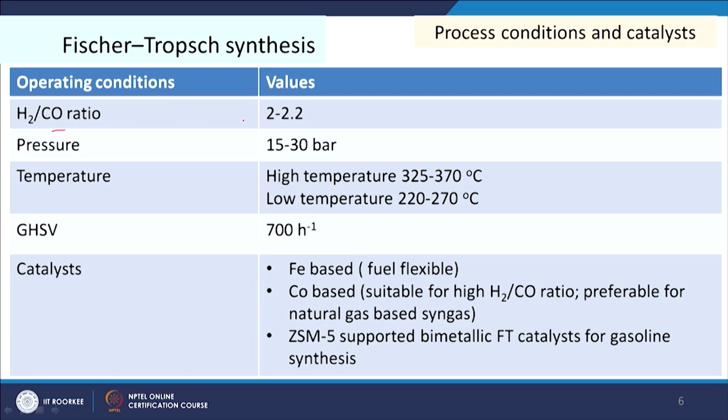So, H2 by CO ratio is 2 to 2.2 and then pressure is 15 to 30 bar, and temperature, as we mentioned, there are two temperature ranges that have been reported, that is 325 to 370 degree centigrade high temperature and low temperature 220 to 270 degree centigrade. Obviously, we will see the variations in the product quality by the application of different temperature ranges.